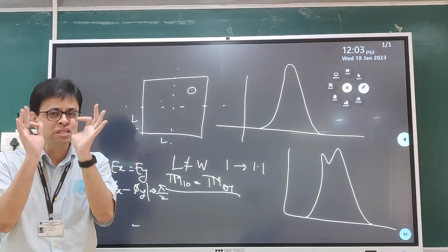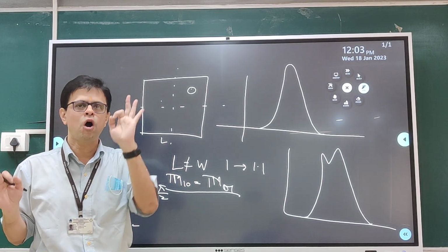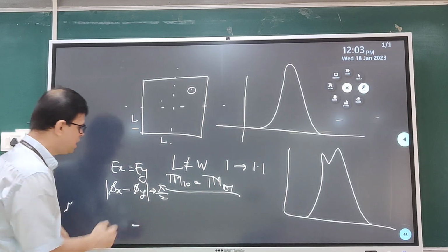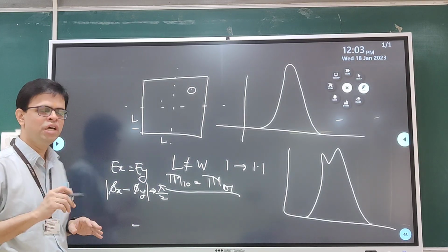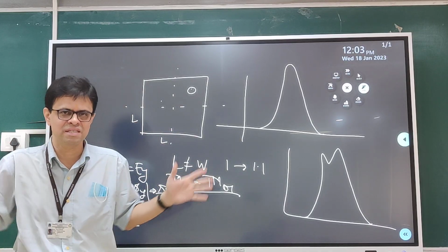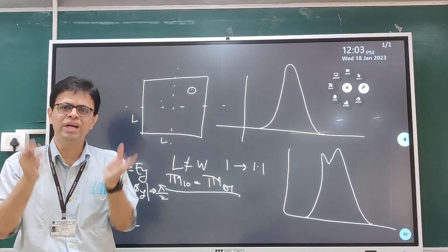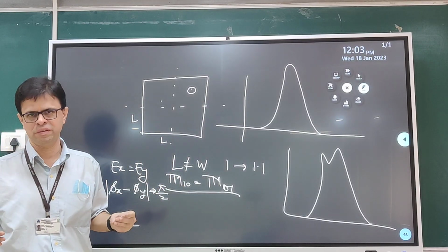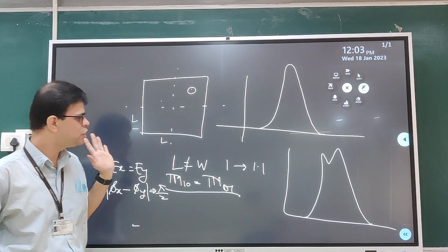So, this is a very important point, I should have optimum separation between the orthogonal modes. That will ensure these conditions which assist CP radiation. Let me tell you, I am using this word assist, because all put together gives me CP radiation. So these are the conditions which assist the CP radiation.